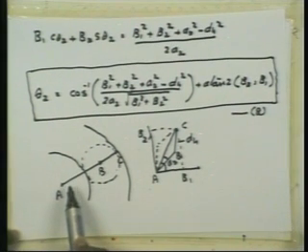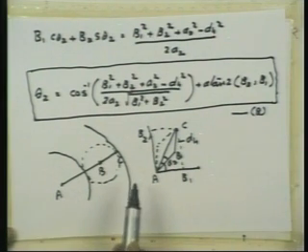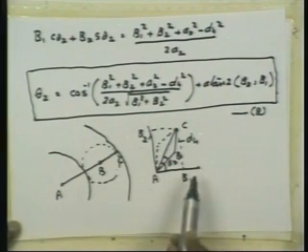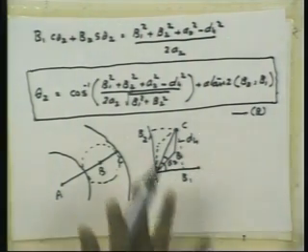And if you look at nature's design, our hand is more or less like that, right. We can scratch the shoulder. So that is actually the configuration which is the maximum volume index, a normalized volume index. Okay, so this is the physical interpretation of this solution.